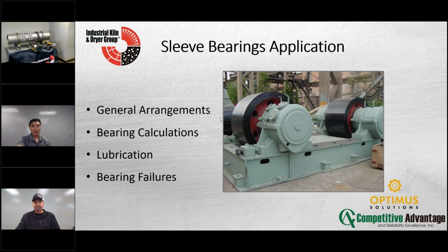Okay. Hey, I'm actually looking at these questions a little bit more. Okay, so here's a question for you, Mike. I like this question. If you have 5 dryers and they're all the same trunnions and bearings, how many spares would you recommend? I would say at least 1 for each unit. Okay. Hopefully that answers your question. On dryers, you got 2 piers. You got 4 rollers on each dryer. Okay, so if you have 5 and you have 1 for each, it covers if that 1 fails. It also will cover if 1 has multiple failures.